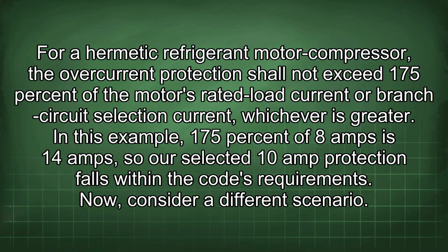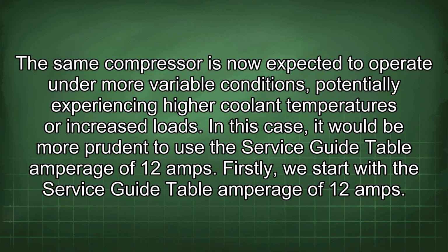Now consider a different scenario. The same compressor is now expected to operate under more variable conditions, potentially experiencing higher coolant temperatures or increased loads. In this case, it would be more prudent to use the service guide table amperage of 12 amps.